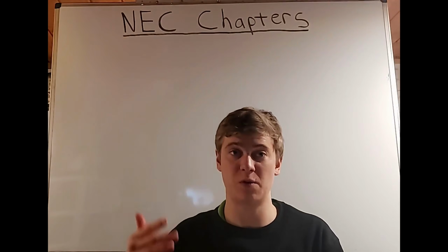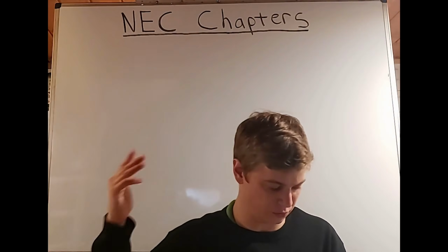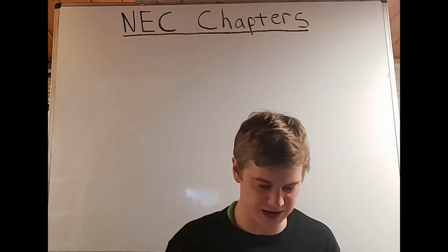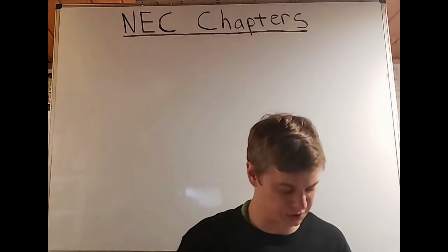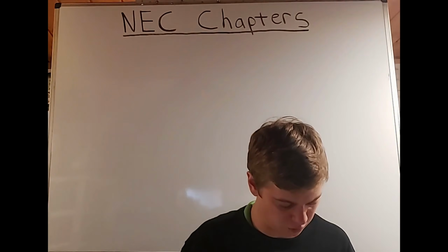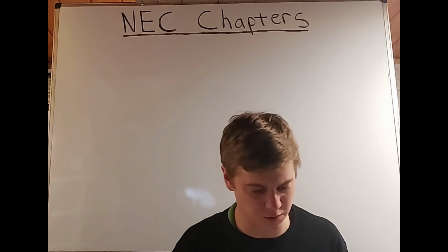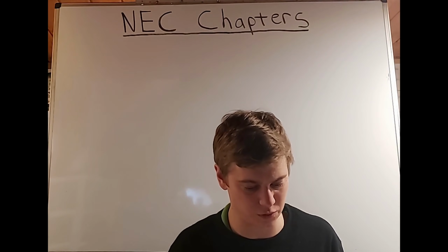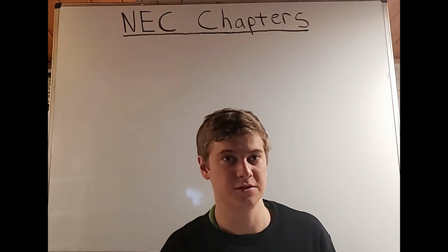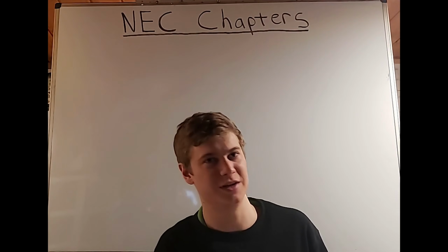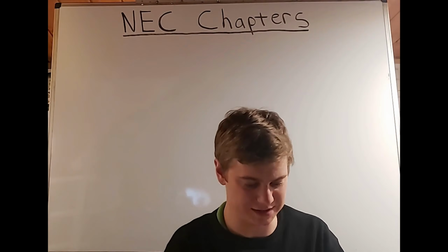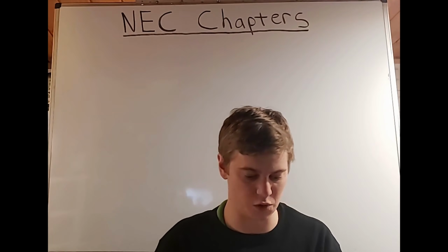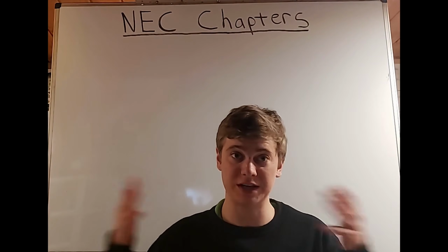Okay, so we'll go over that one more time. We have 1, the depth of the working space. The ace is the dead front, and at the bottom of that does mention where you have rear access required to work on non-electrical parts of the back of enclosed equipment. You have a minimum horizontal working space of 30 inches. So that's non-electrical equipment. I don't know if they're going to talk about that, but that is here in the book. 2 talks about the width of the working space, and you have a 30-inch minimum.